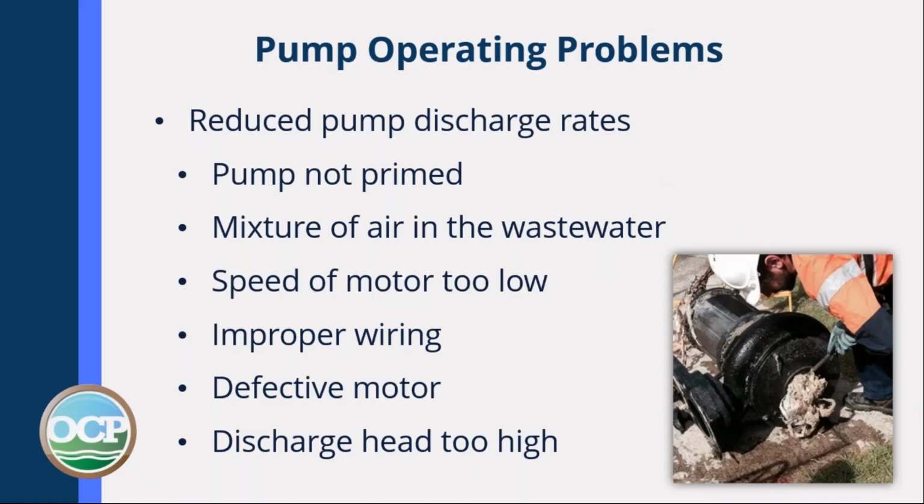If you're having reduced pump discharge rates, check to see if the pump is primed. Make sure you're not getting a mixture of air in the wastewater. The speed of the motor could be too low. You could have improper wiring. There might be a defective motor or a damaged impeller. Maybe the discharge head's too high.